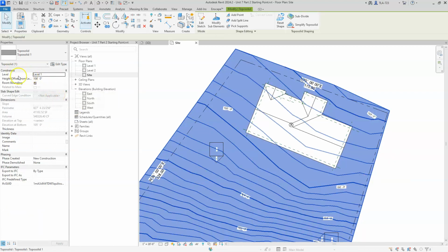You'll notice there are no instance properties that define the material that can be assigned to it. But we know through our vast experience working with components and families in Revit that there's going to be some place that we can apply a material to it. So if it's not in the instance properties, you're probably good at guessing that it's going to be in the type properties.